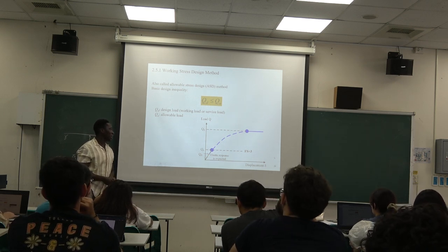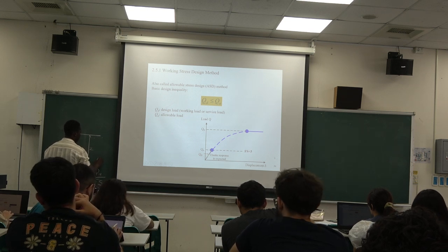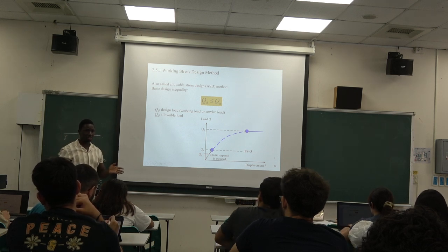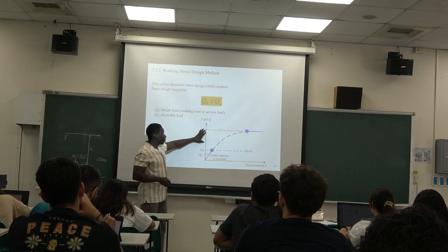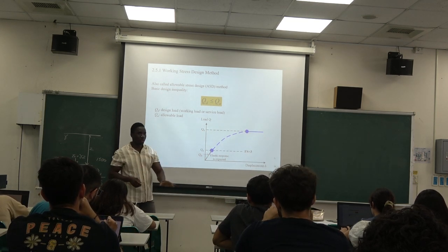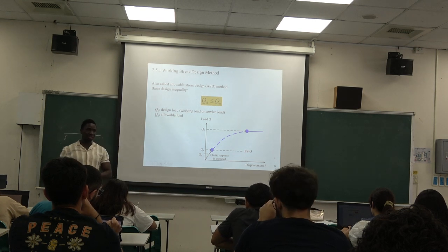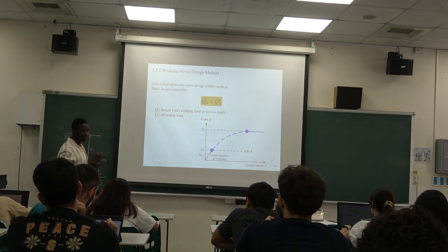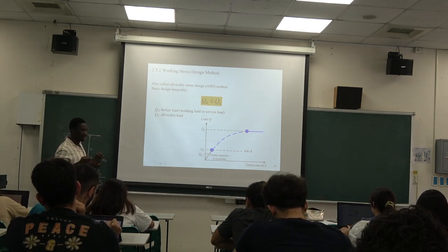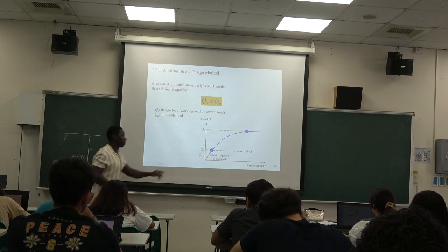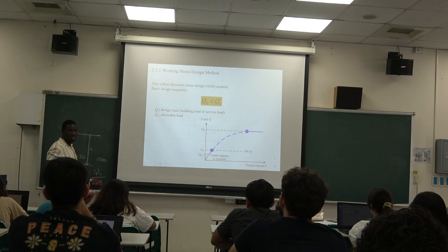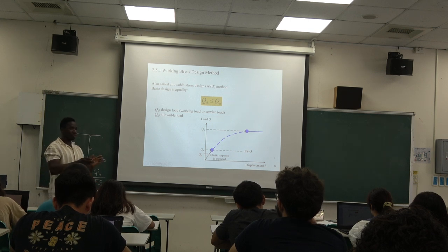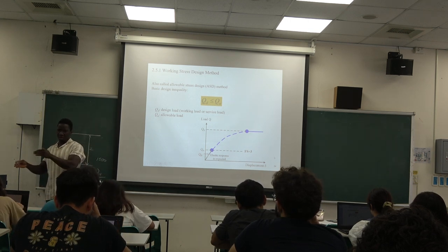Okay. We know, for example, that if that is 1,500, but we are dealing with soil, there are so many uncertainties. I know if I put a maximum load of 1,500 on this, it will fail. When I'm doing the design, do you think it's a good idea for me to set that value to 1,500? No, because there are so many uncertainties. So we will divide this ultimate value by the factor of safety. Okay? How safe do we want this structure to be? So you might have 1.5, you might have 2, you might have 3.